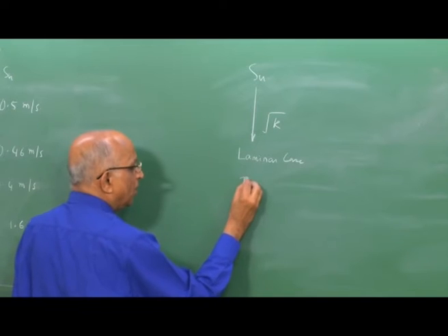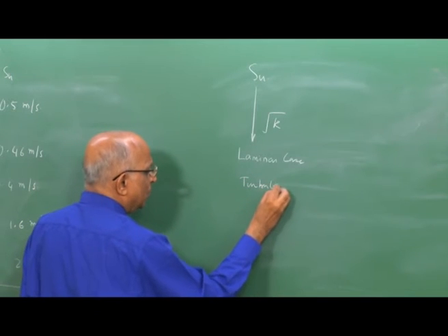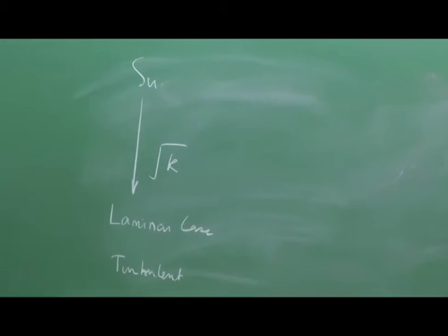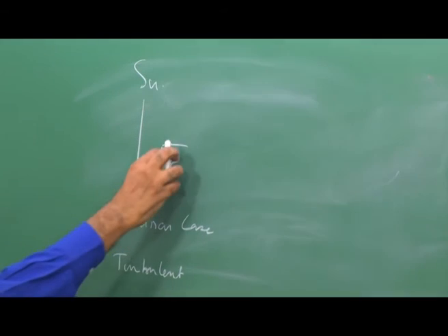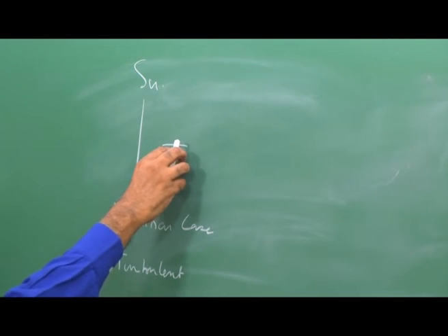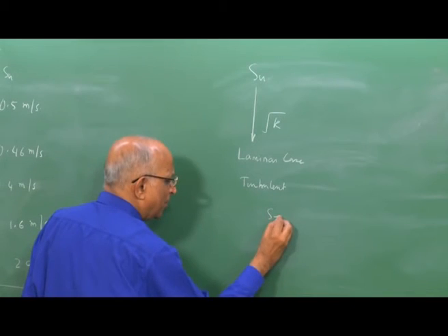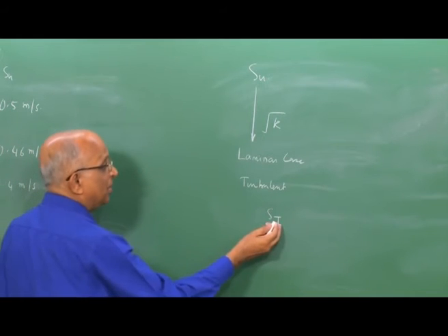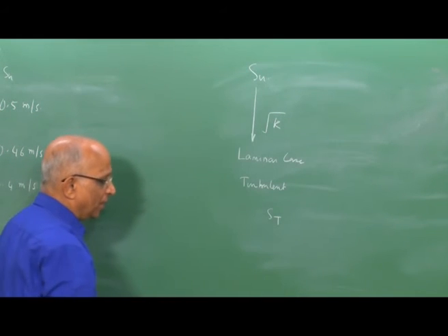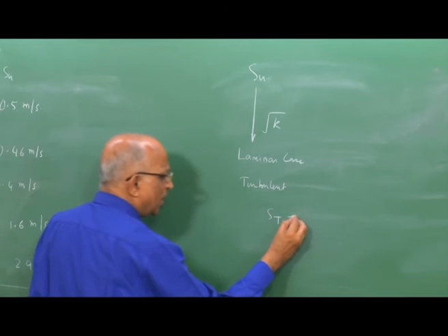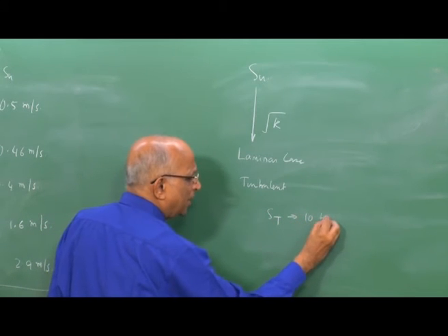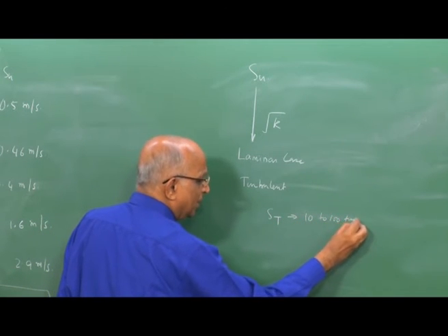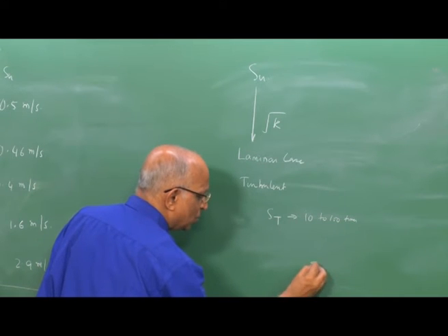If it is going to be turbulent, well, I can use similar expressions, but I must also take care of eddies which increase the value of the thermal conductivity, and therefore, I can also say, well, the flame can move at turbulent speeds, which I call ST, as compared to SU over here. The turbulent flame speeds are generally around 10 to 100 times faster, because the transport of heat from the ignition source or into the succeeding layers is very much higher.